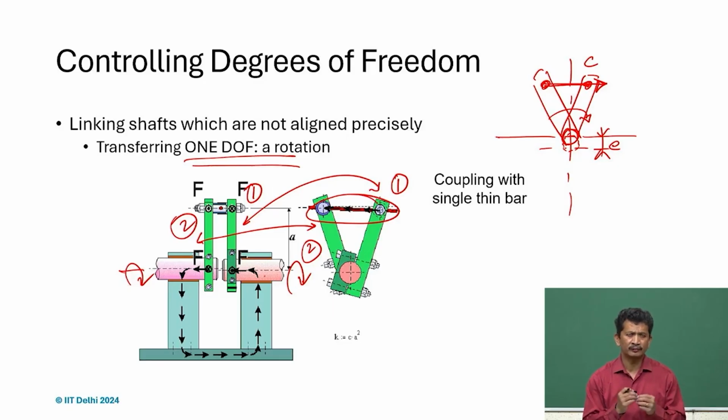So, if there is any eccentricity in the shafts at the point of location where we put the arms, since it is an articulated link, it can move, it can shift a little bit and accommodate that, and even though the position is varying, it can change. So, the articulated link is good enough.